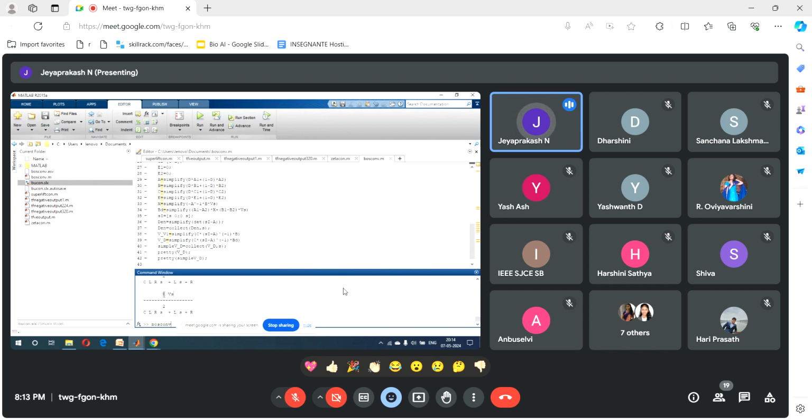So we get R into Vs divided by CL R S squared plus L S plus R. In the denominator I take R outside, so the numerator and denominator R will be cancelled. So we get LC S squared plus L by R S plus 1. That is the standard series RLC formula. We get the series RLC standard transfer function.